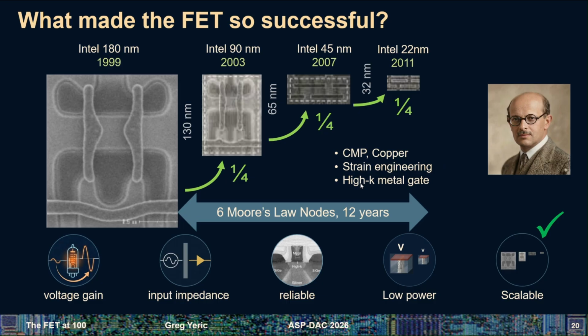And then also in this era was the high-K metal gate. So the dielectric constant of the silicon oxide, as we shrunk the device or had trouble shrinking the device, was such that we couldn't build enough electric field with the voltages we wanted. So we went to higher K, hafnium oxide most commonly, so that for a given voltage we could develop more electric field across the gate dielectric, and then influence the on-off characteristics of the device better.